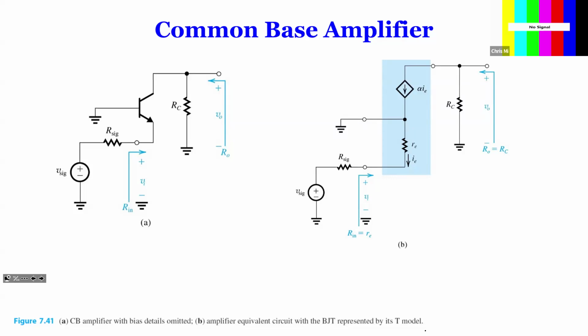Okay. So what you do is you go find the small signal equivalent circuit of the BJT, which we know here. And you guys know that for the BJT equivalent circuit, again, we're going to use the T-model because, as I said, every time you find there's something connected at the emitter, if the emitter for small signal cannot be grounded or the source cannot be grounded for small signal, you always use the T-model. That will make your life much simpler, much easier. So the T-model says that you have a current source over here.